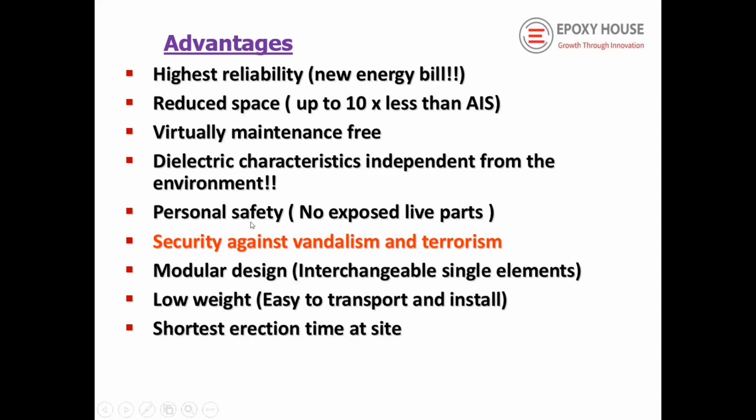Personal safety is very good because there is no chance of explosion related issues. In the case of air insulated switchgear, any component can get damaged, or it can be broken, or it can be blasted, and it can lead to personal injury. AIS is more lethal than the GIS. Security against vandalism and terrorism is also better.